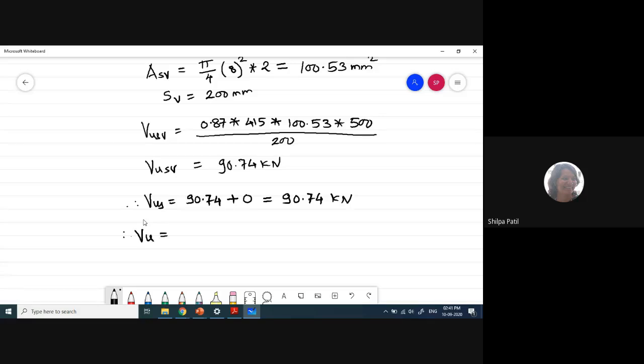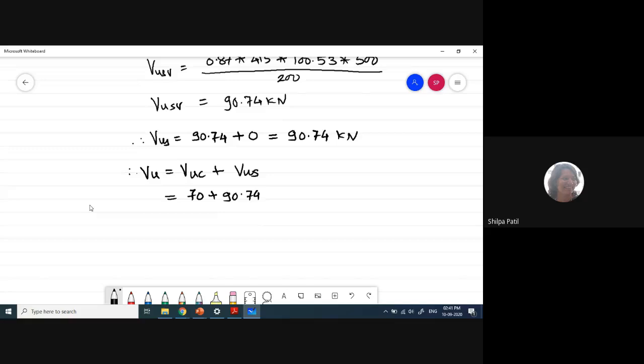VU is, I will write down again, VUC plus VUS. First of all, tell me VUC value. 70. 70 plus 90.74. So VU is coming as 160.74 kilonewton. Okay, this is VU.